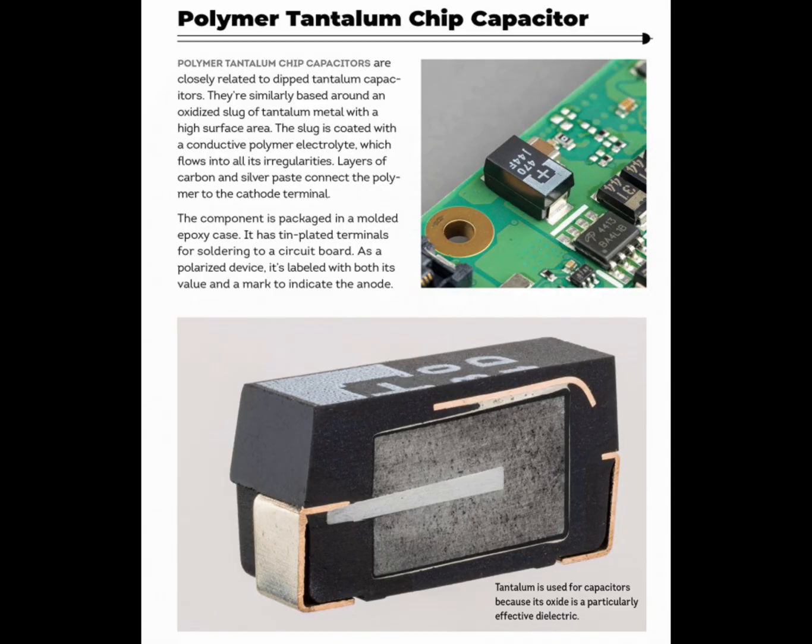Polymer tantalum capacitors often have better performance over temperature ranges compared to traditional tantalum capacitors. The polymer electrolyte typically has lower leakage current than liquid electrolytes. They are used in smartphones, tablets, and other portable devices. They are often found in motherboards, graphic cards, and power management circuits. They are also used in base stations and networking equipment.